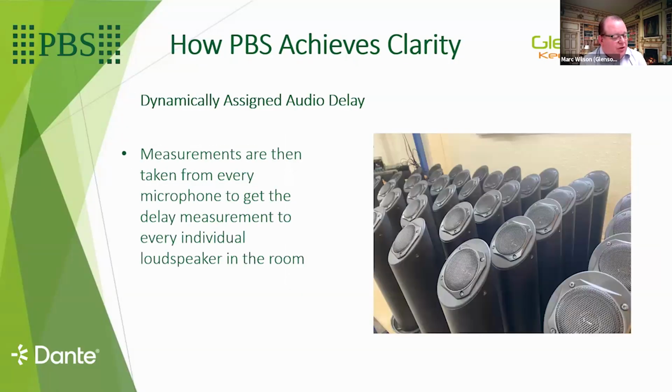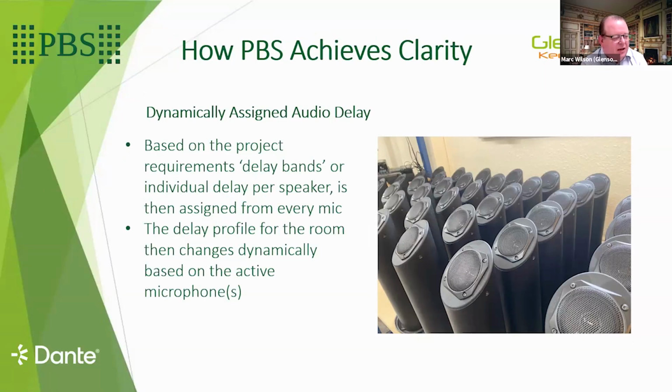We then take measurements from every microphone to get the delay to each individual loudspeaker in the room. So if we've got 300 mics and 500 speakers, for every mic we need to know the delay to all of the 500 speakers in the room. We might not use them all, but we start by knowing the information, because that allows us to then work on the delay profiling. So we need those measurements of delay from the microphones to every speaker.